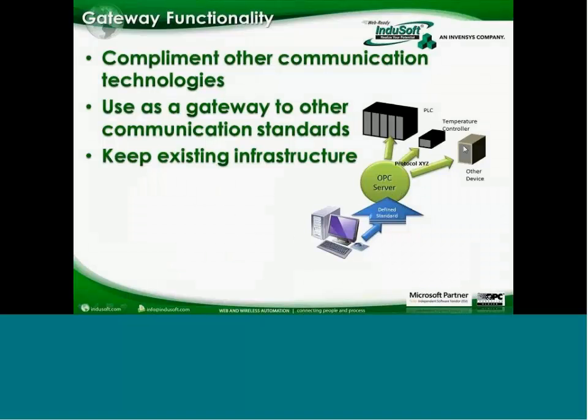Now, let's say that you wanted to get information from these PLCs, temperature controllers, and other devices to other communications devices that you already have. We could potentially communicate and store data from those devices into a SQL database. We could hand that off to an ERP or an MES system. We could be communicating with one of the over 240 drivers that InduSoft has built into it to other PLCs or other drives, temperature controllers, for example.